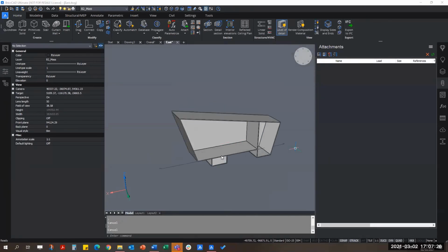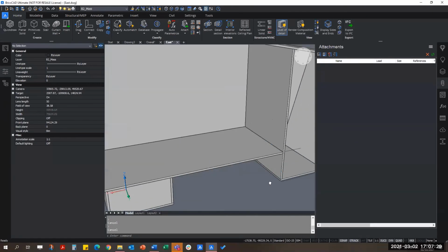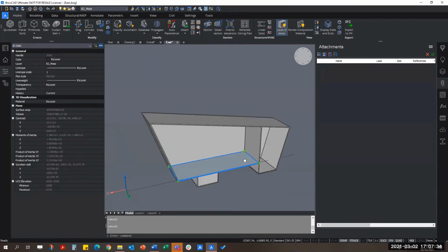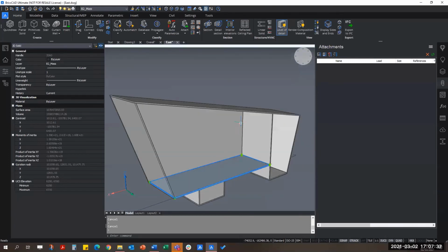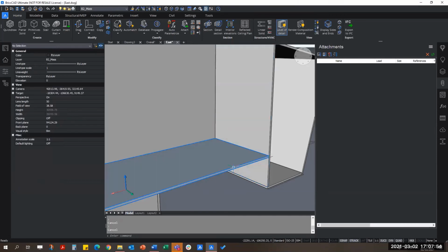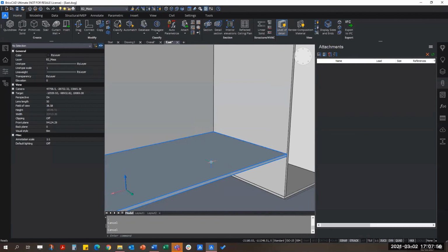Now that I have got this wall set here, I would like to bring this floor plate upwards. I'm going to duplicate maybe 3 or 4 floor slabs up here. And what I could do is, obviously, revert back to your normal shortcuts, just like you do with Pro or with BricsCAD Lite, which is copy, CO. However, in BricsCAD BIM, we have something called BIM copy, which essentially copies your selected entity together with its metadata, if applicable.